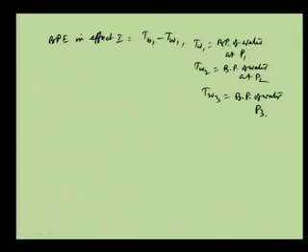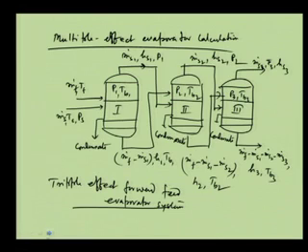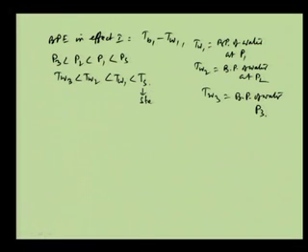That is when these pressures are maintained in the subsequent evaporators. So, we can say that P3 is less than P2, which is less than P1. So, we know that Tw3 is less than Tw2, which is less than Tw1, and that also should be less than Ts, which is the steam temperature, and this corresponds to Ps, the steam pressure. Okay. So, this is the external steam temperature that we know.